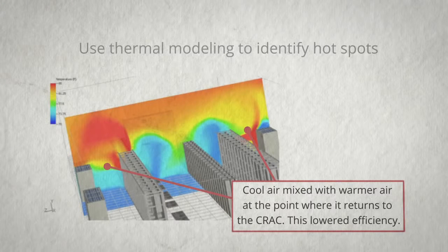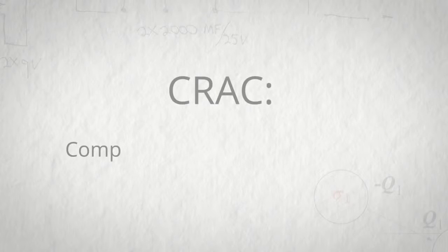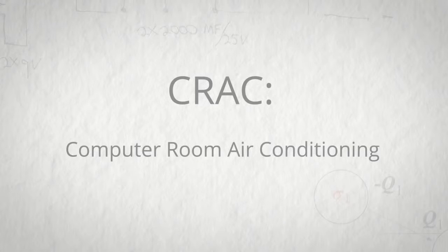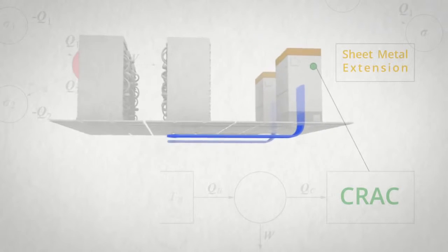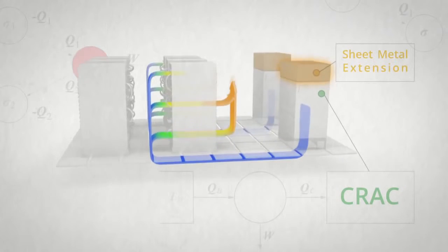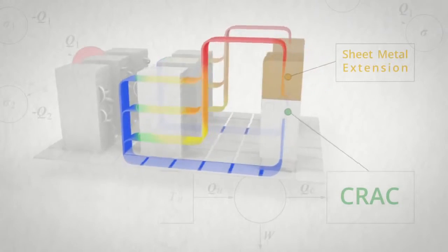For example, in one of our computing and networking rooms, we call them CNRs, we did some thermal modeling to see exactly what airflow was doing. Through that modeling, we realized that the intake to our CRACs was too low, and that by simply piecing together some sheet metal, we could create extensions that would dramatically increase the airflow quality into the CRACs. We also did a bunch of other retrofits.